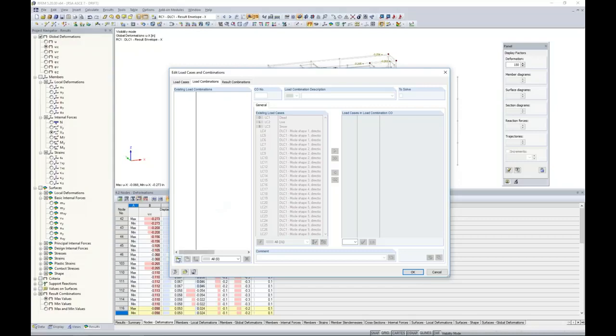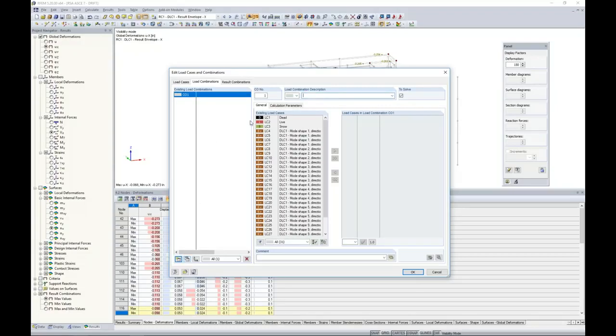And what this includes, if we create a new load combination here, is 1.2 dead plus live plus 0.2 snow, and eventually we'll add in our earthquake as well. But for these gravity loads only, I change around my load factors here to reflect what the code tells us. So 1.2 dead plus live plus 0.2 snow. So now I have this existing load combination with only gravity forces or axial loads.